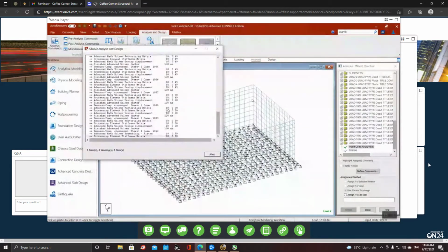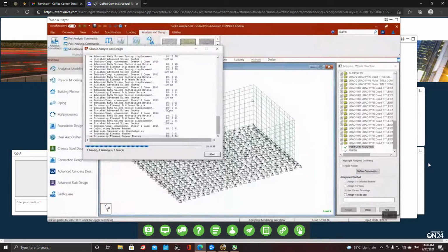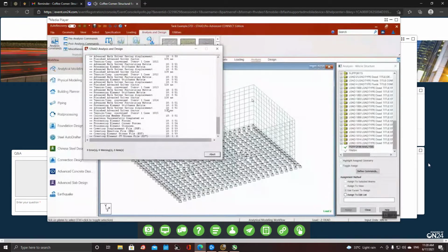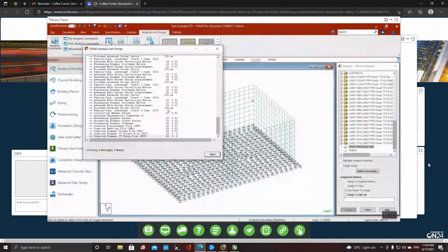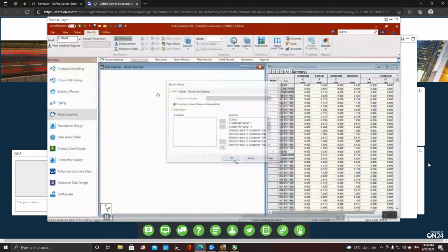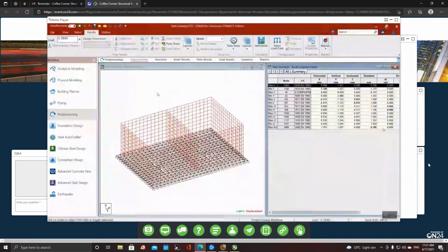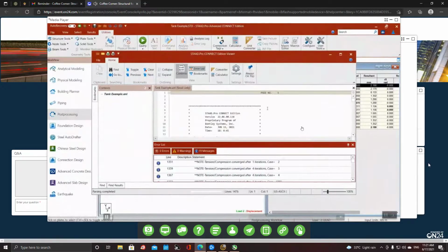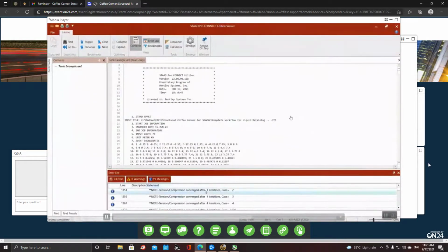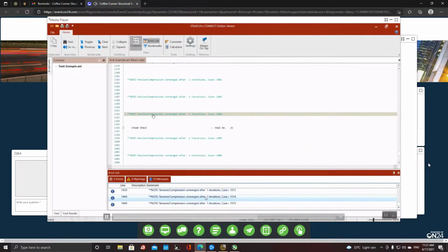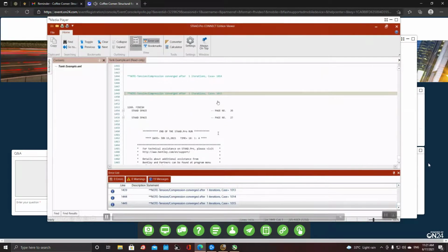You can notice that since the springs are compression-only springs for the base slab, StaadPro will do an iterative analysis. You can see the program reports that tension compression converged by iteration 1 for each load case. So make sure the load cases are all converged. And I check the post-processing results: deflection 2.18 millimeter. That is reasonable. And view the output file. Make sure there are no errors or warning messages, and note the message which says that the tension compression is converged for all the load cases.